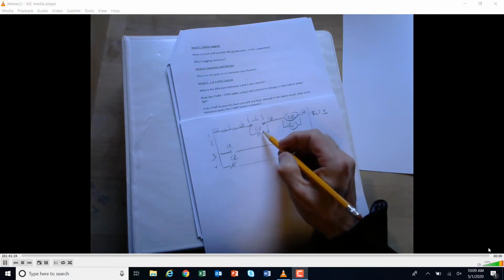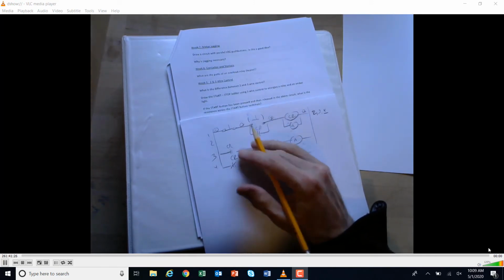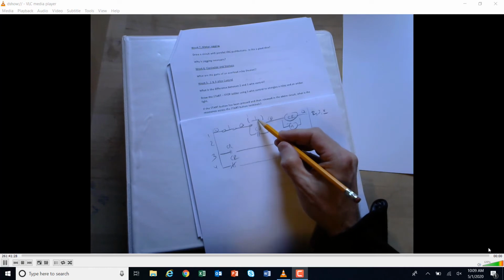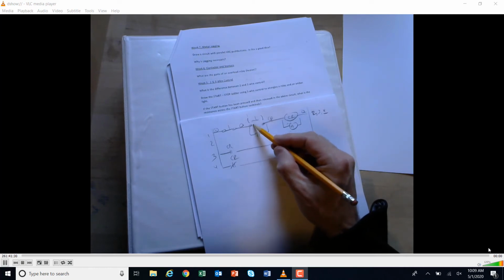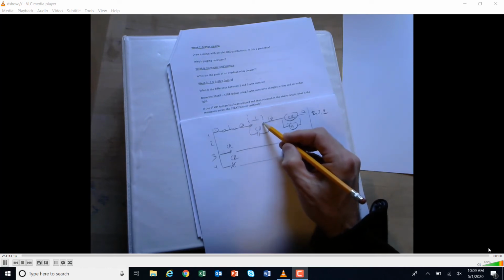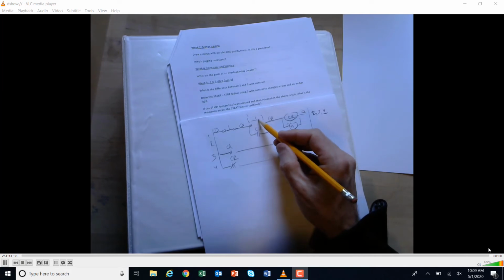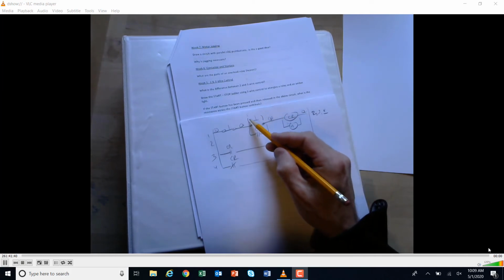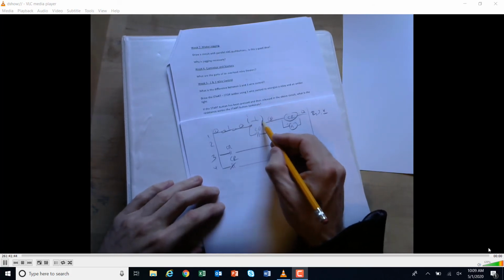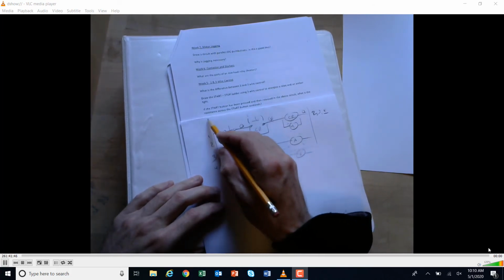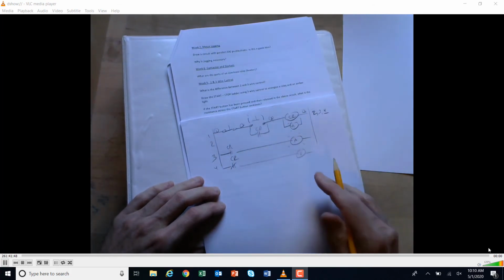Or if this system was de-energized, and you measure across there, you would get infinite, because this would be open and this would be open. But once you energize it, once you start it, you've got to remember, if I'm checking resistance, what am I checking? Am I checking this, or am I really checking this device, or am I checking through the transformer? Things like that.